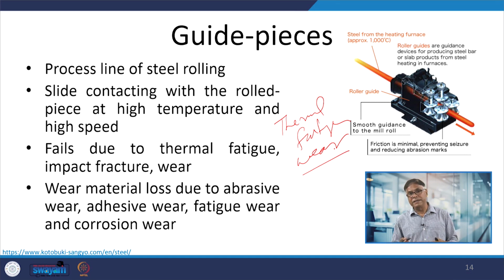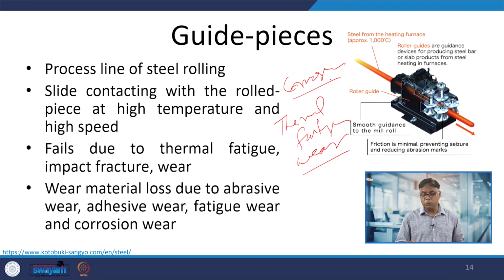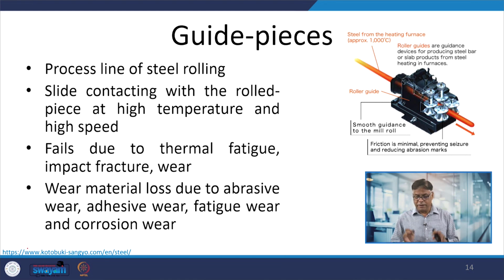So, to maintain the temperature of the guide pieces also, sometimes coolants are used. These coolants, if not clean or very acidic in character, will interact with the guide pieces and form corrosion products. These corrosion products eventually lead to the wear of material from the guide pieces. So, it is important to understand that these hostile and very severe working conditions